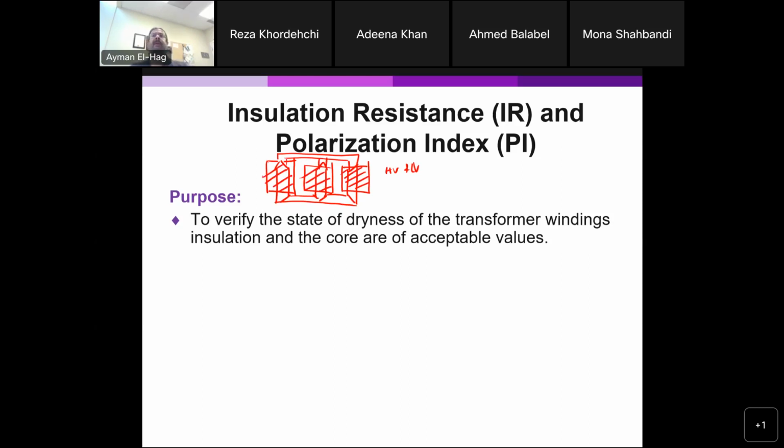Now in this active part, because you build it in the factory, there's humidity, and the insulation system will absorb part of this humidity. Also, we use insulation paper between turns. We use a specific material, and that material has glue in a diamond shape. If you look at the paper, you will see those diamond shapes of glue, and that glue will be activated at very high temperature.